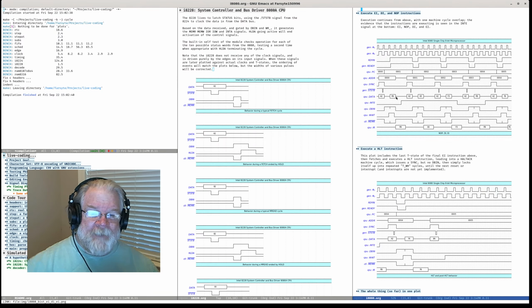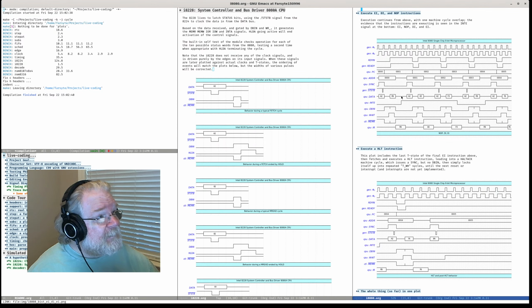I wave my hands over some things. When you set this data bus to high impedance, it will mark it as high impedance, but the value is still there. So you can still look through something high impedance to get the value that was there a moment ago. This makes it so that our simulation can continue and can run efficiently. So we have IR set to FB. This is the interrupt enable instruction. And we do indeed see here that the int E line,